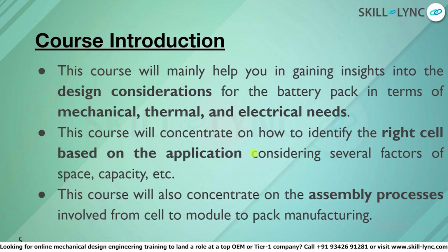So not just that, we'll not limit over there. We'll also understand what are the different kinds of ingress protections needed to make sure that the pack is sturdy. And ingress protection is something like when a foreign object like water or dust enters into it. So that is also a most important part of battery pack design.